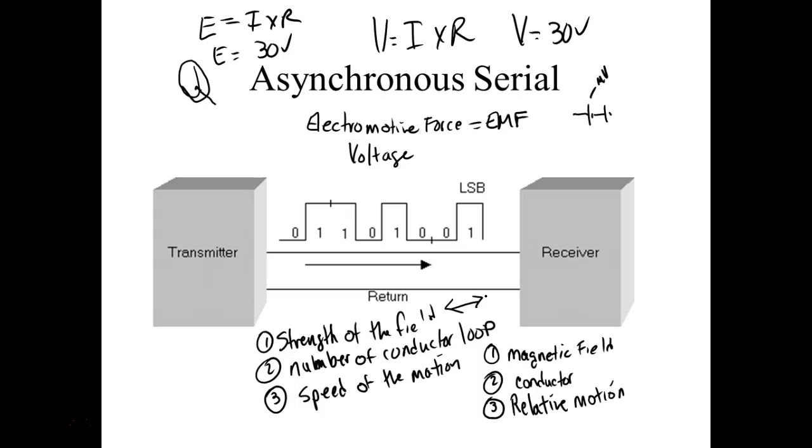So that's the way, right off the bat, you can tell if your alternator's working. You can go out and get a voltmeter. If you have to jump your car off, jump it off. Look across your battery. If it's measuring 14 volts, it means your alternator's fine, but your battery won't charge. So what would that mean? That usually means you got a loose connection or you got a bad battery, right? If that makes sense. So you can tell in a heartbeat.